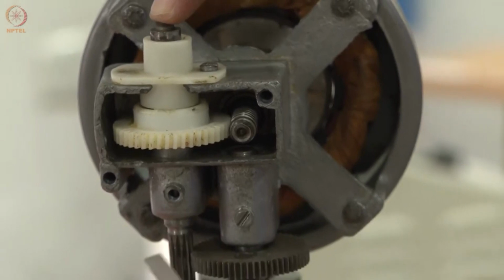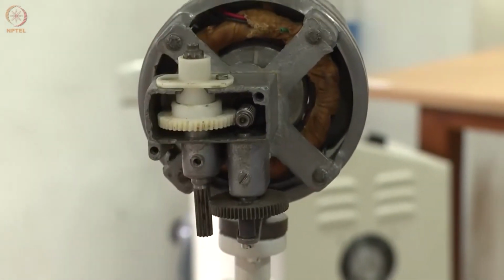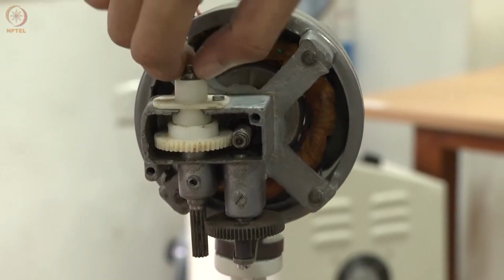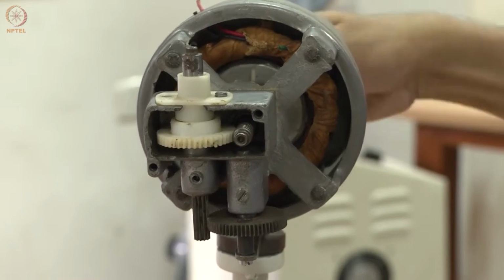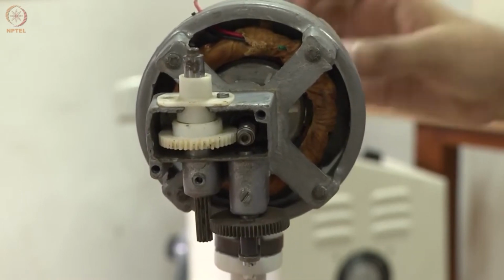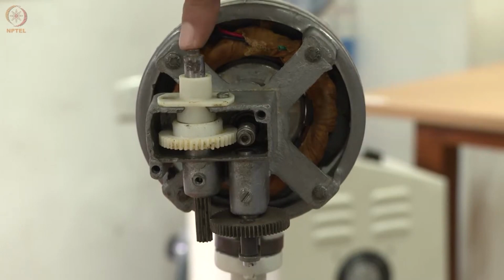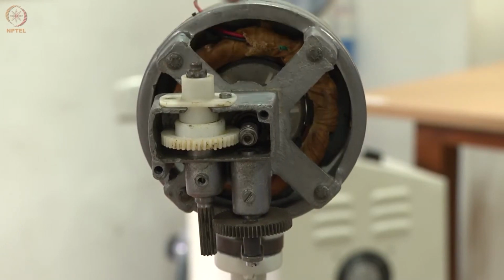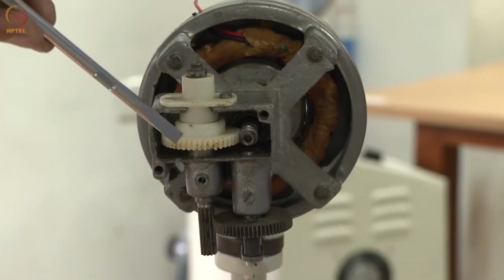Now when you engage the oscillation mechanism, this mechanism is broken, so it is not engaged. In practice what will happen is, when you pull it up, now it is disengaged. So the worm wheel and worm are always in contact. The worm wheel will always be rotating. What happens is, when you press the oscillation on button, that basically locks this shaft that you see here to the worm wheel.